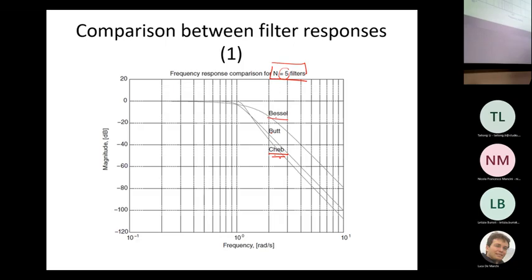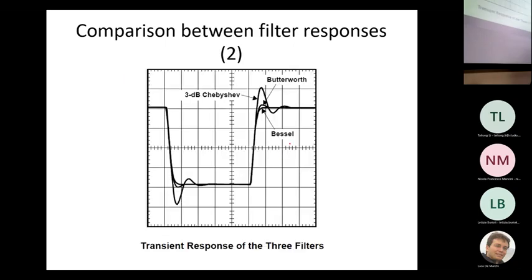However, the Chebyshev behavior is slightly worse as far as the step response is concerned, because since the distortion is larger, when you feed your filter, for example, with a square wave, what you get is this huge ripple effect in the time domain. So this is a time waveform. Please do not confuse ripples in the time domain and ripple in the frequency response.